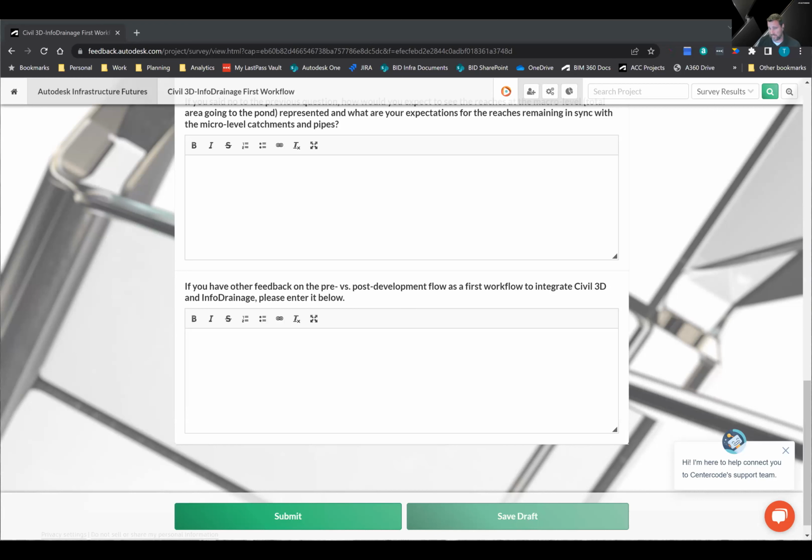I assume what you're getting at is that parcels let you break up areas by soil and ground cover to quickly get your runoff and curve numbers, which the catchment tool doesn't do, but I know people use either parcels for that or maybe a Map 3D workflow. So we'll have to get into details on how that would work if this is where we start to dive deeper.